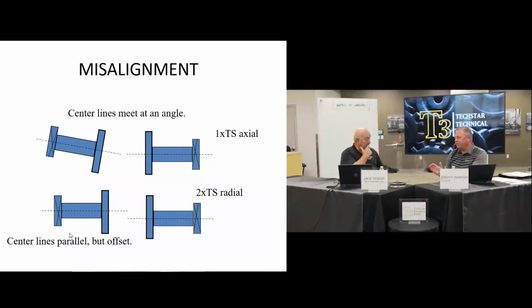So in that case, were you looking at the vibration data to verify, yes, I have a misalignment, and then you put your alignment tools on the machine and confirmed it? Yes, they actually had an online monitoring system, and none of the radials were showing any type of high vibration. Everything looked kind of normal. Only the axial position was showing an increase.